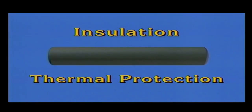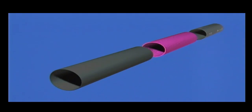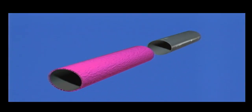To minimize the amount of heating required, or maybe eliminate it altogether, we often insulate the tank car. The most common insulating materials used are fiberglass and urethane foam. They will range in thickness from about 4 to 8 inches.